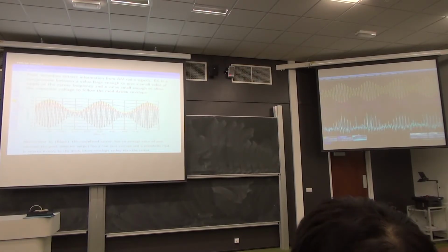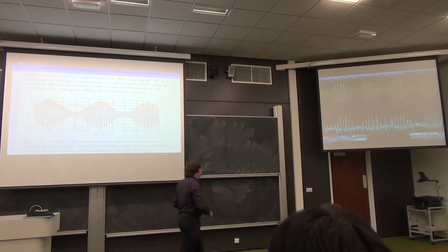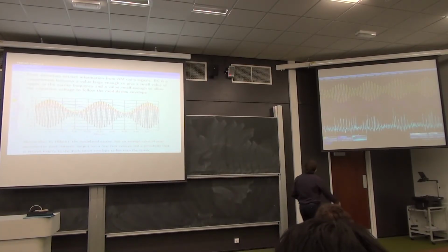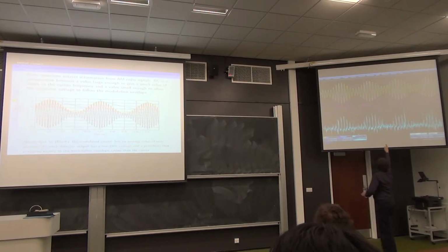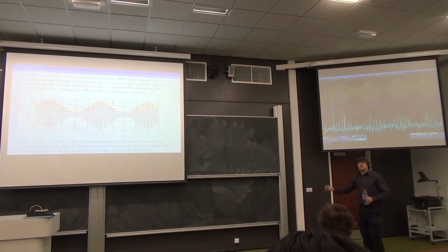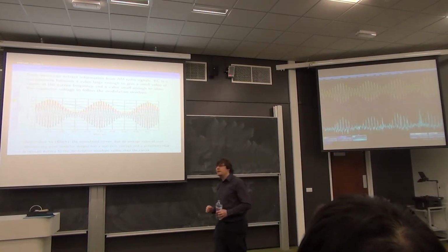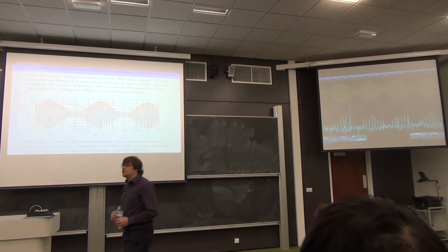In the case of this setup we have here, even at the lowest part of the input cycle, just about here, just about there, and about there as well, we can still see there's a little bit of ripple from the peak detector. That's the critical thing. If you don't have a little bit of ripple there, your time constant is too big.